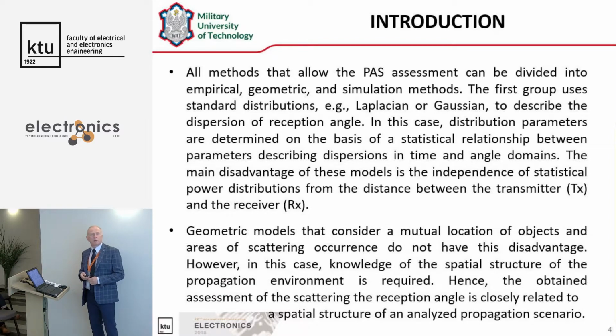All methods that allow the power angular spread assessment can be divided into empirical, geometric, and simulation methods. The first group uses standard distributions, for example, Laplacian or Gaussian, to describe the dispersion of reception angle. In this case, distribution parameters are determined on the basis of statistical relationship between the parameters describing dispersions in time and angle domain. The main disadvantage of these models is the independence of statistical power distributions from the distance between the transmitter and receiver position.